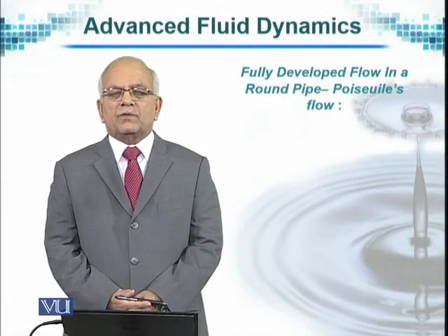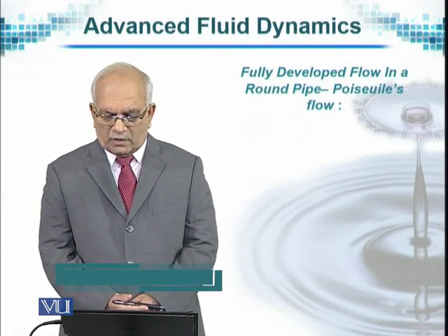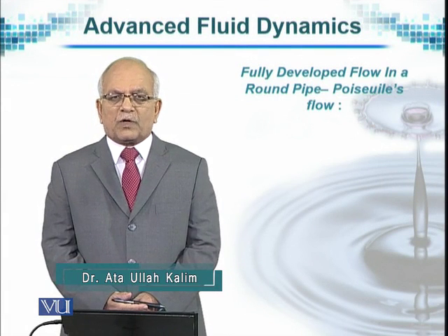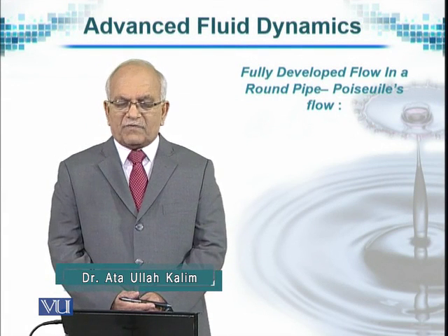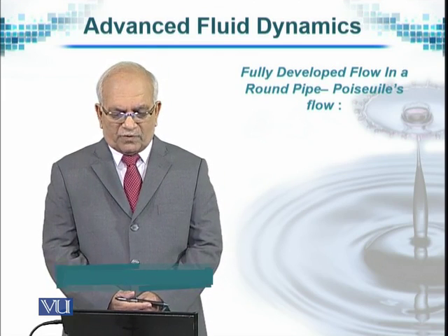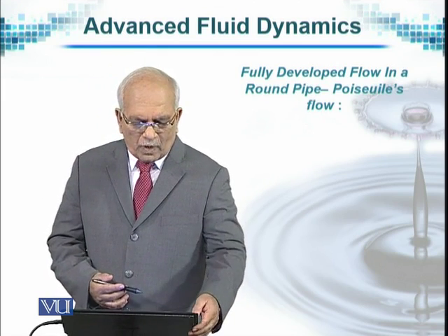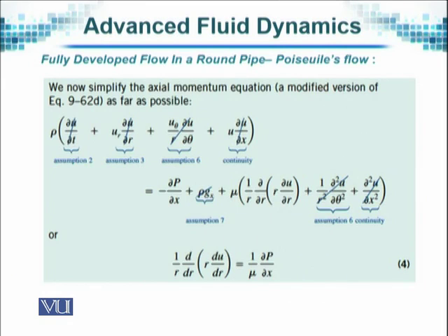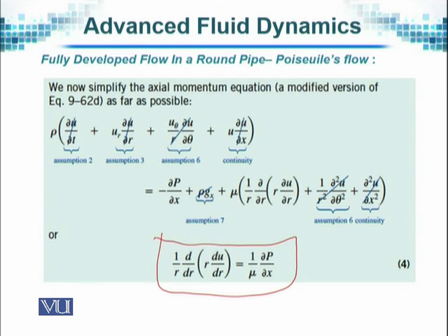We continue with determining the solution of the Poiseuille flow. We have determined the non-zero term coming out of the continuity equation, and now we try to determine what we get from the momentum equations. If you write down the equation, then you obtain only this as non-zero terms.